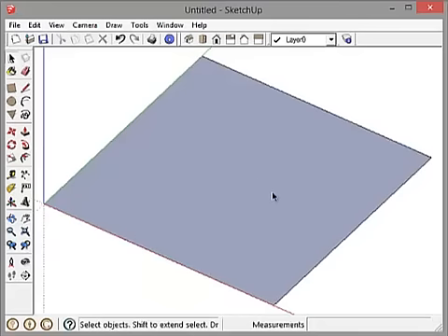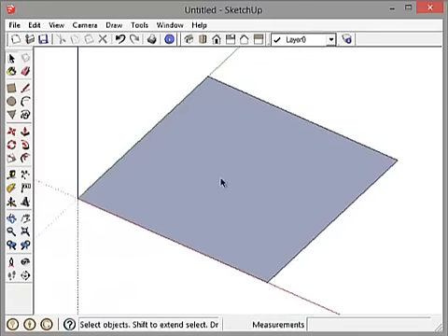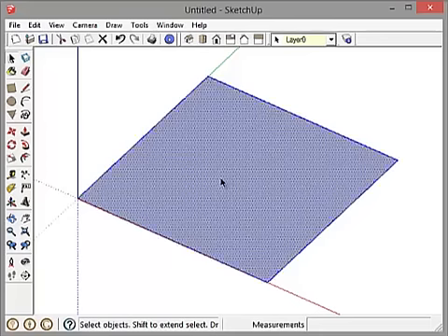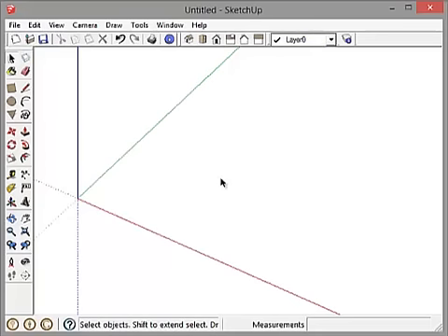And now that I've got the window filled, I'm going to back off just a little bit and then delete that rectangle. Now I know that when I open the window, this window is roughly 12 inches by 12 inches. And so when I start drawing things, they will look like I might think they should look if they're roughly 12 inches by 12 inches. So the last thing now is to save this, and I'm going to save it as a custom template.